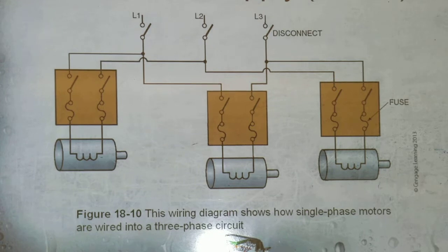This is typical, and you're gonna see a lot of three-phase units out there. They're wiring the single-phase motors on that unit this way. A lot of times, the only thing that's three-phase on the unit is a compressor, and then sometimes a blower. Very rarely are the condenser fan motors three-phase.